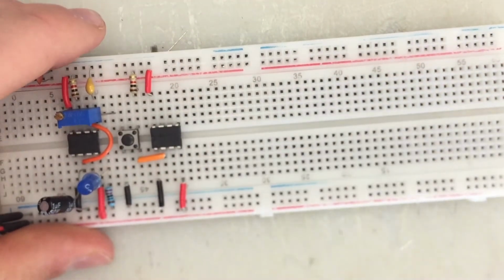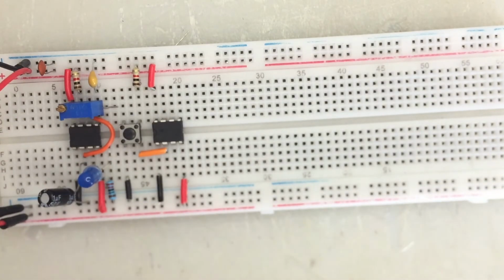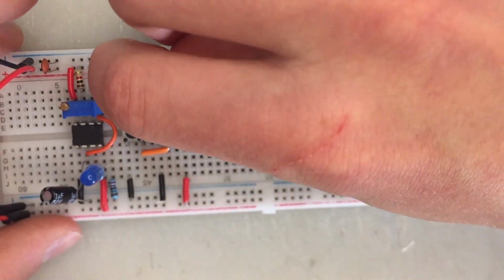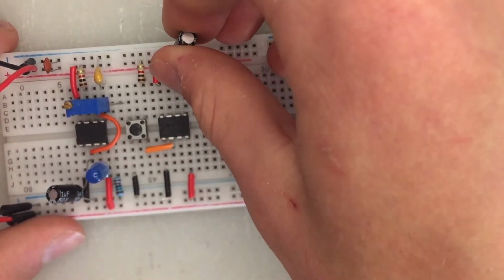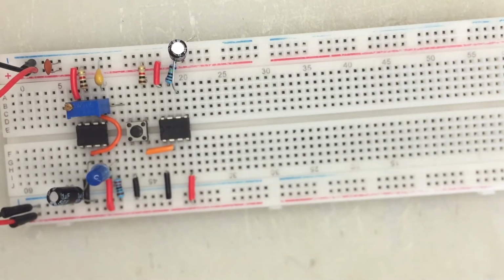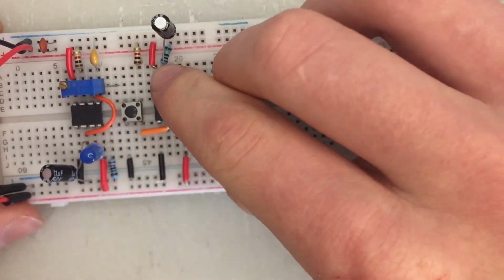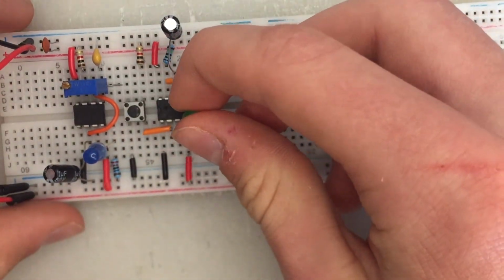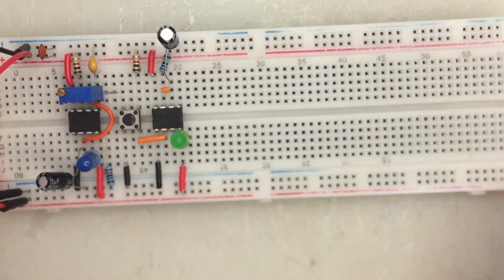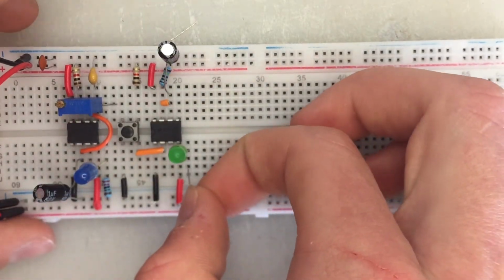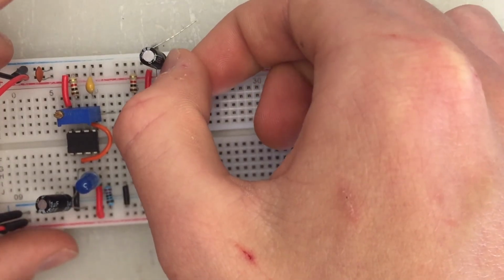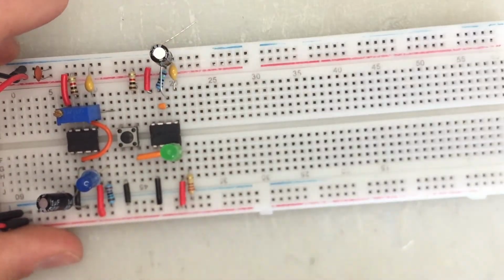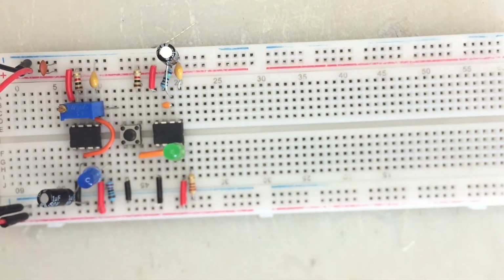to 5 volts. Now I can connect the 1 mega ohm resistor from 5 volts to pin 7, and for now I'll just connect the 1 microfarad capacitor from ground to pin 6 so we can actually visualize the LED staying on. And now I'll connect pin 6 and 7 together. I'll connect an LED to the output of the 555 timer, and then put a 220 ohm current limiting resistor from the LED to ground. Lastly, I'll connect a 0.01 microfarad capacitor from ground to pin 5.